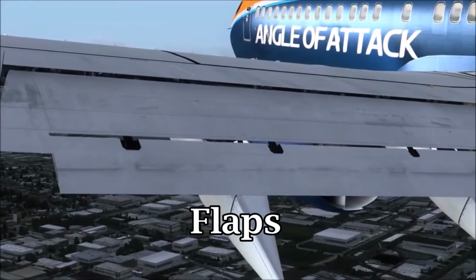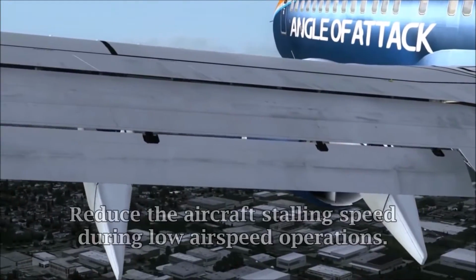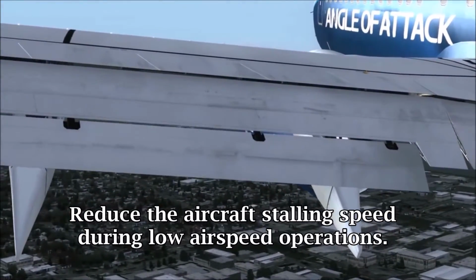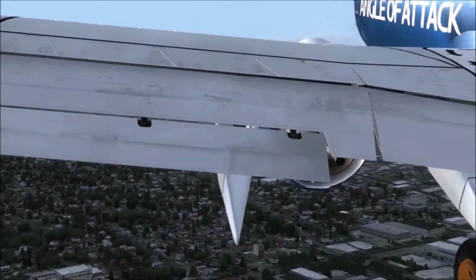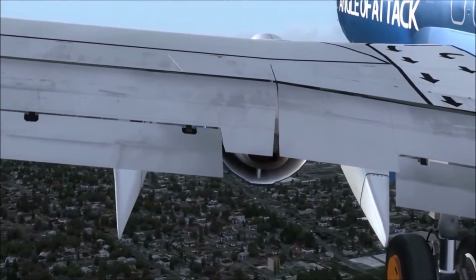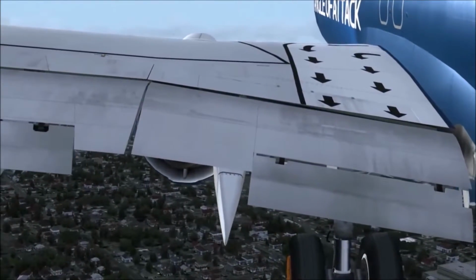Flaps are movable devices in an aircraft's wing that modify the wing shape to achieve extra lift and reduce the aircraft's stalling speed during low airspeed operation, such as while taking off or landing. Flaps may come in various forms and shapes, but they commonly extend aft of the trailing edge of the wing. Like this, the total wing area increases and there's higher room for generation of lift.